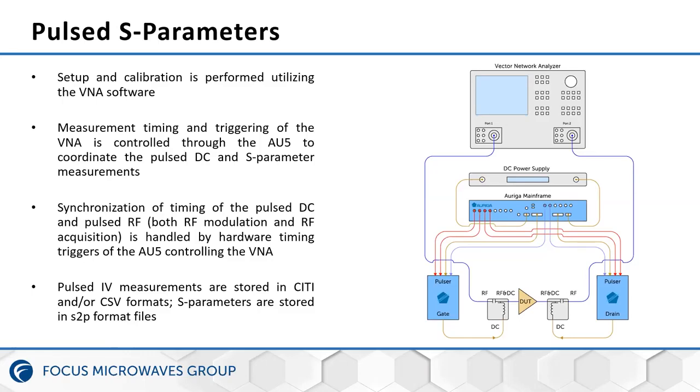For this measurement, the pulsed IV system is synchronized with a vector network analyzer. The pulsed IV system acts as the primary trigger, and the delays within the vector network analyzer are adequately used so that the pulsed S parameter measurements are always made within the stable regions within the pulse. So the choice of IF bandwidth and delay has to be very precise.